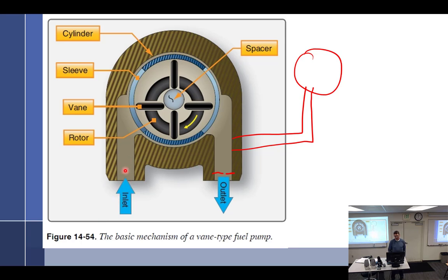All together now. Constant displacement. So otherwise fuel would come up to here from the boost pump, get to right here and do what? Stop. And do nothing. Right? So I can't get it through, on, and into the fuel control unit to prime it out. So then I can get fuel to here, then I hit the starter.